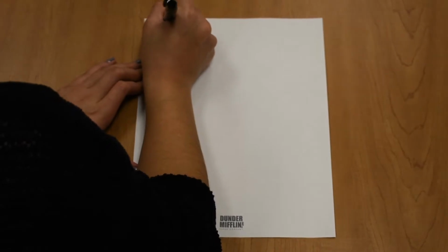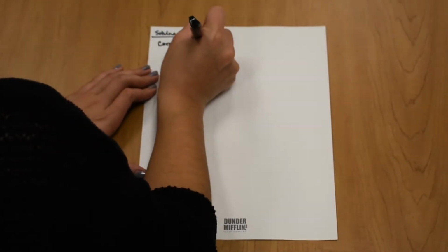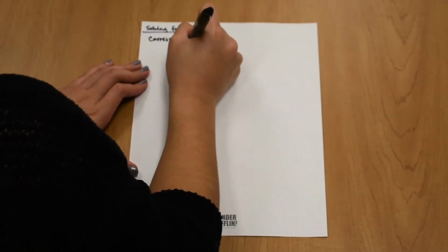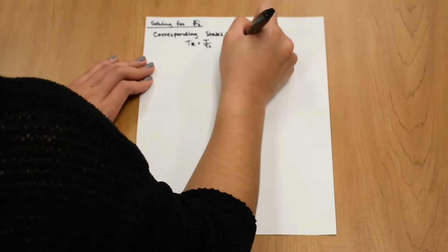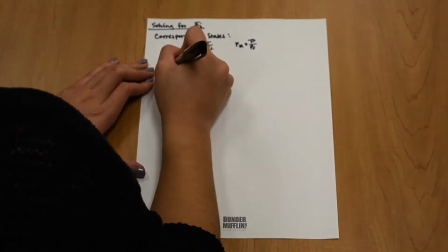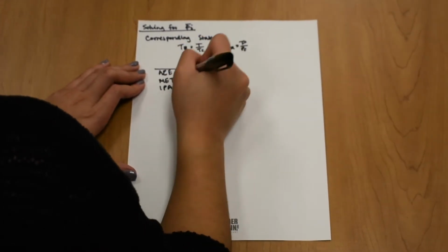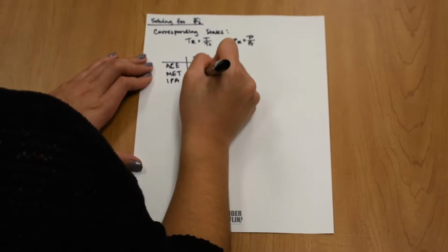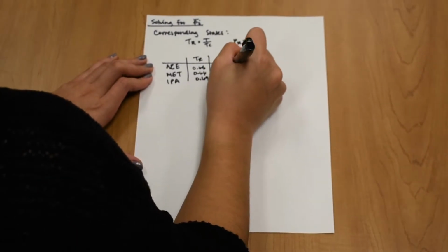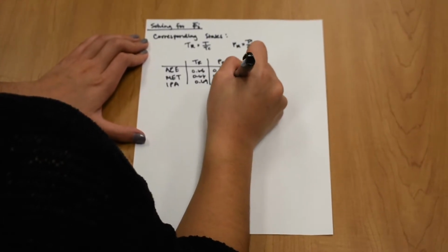To solve for the fugacity coefficients, we use the principle of corresponding states, which generalizes that the properties of a gas are dependent on intermolecular forces and are related to the critical properties of the gas. When two fluids have the same values of reduced temperature and pressure, they are said to be in corresponding states. To calculate the reduced temperature and pressure, we use literature data from Perry's Chemical Engineers' Handbook and 1 atm pressure because the system operates at atmospheric pressure.